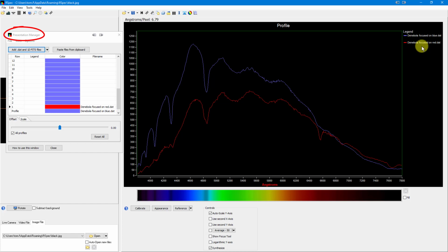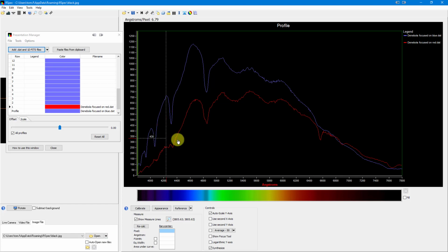Okay, that was a lot of introductory comments, wasn't it? But it will only take a moment for me to show you how easy this feature is to use. First, if this panel is invisible, click here. Then add a check mark to this Show Measure Lines box. When we first check this box, the measure lines won't be visible at all. They're still off screen. I'll grab one of them here and drag it onto the screen.